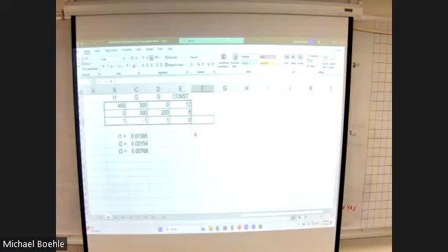Okay. So if I want to know, in this case, voltage 2, I could just say, well, that's going to equal that current times 300 ohms, right? Because I put all the resistances in ohms, that means all the currents are in amps. If you put all the resistances in kilo ohms, all your answers will be milliamps.